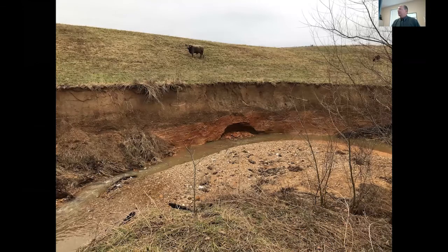So in a pasture situation, we have this too. A lot of times we'll look at stream banks in pasture where cattle have aggravated the problem too. Here you kind of see the start of a rotational slump that's developing in the channel, and you can see, if you have a large enough screen, hopefully, that there's a definite difference in soil texture and properties here on this outside curve of the channel. It's developing this point bar here, and the elevation and locations of these point bars are a key indicator that we look for in the field.